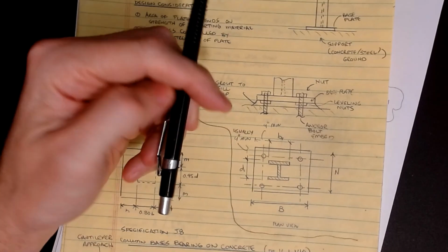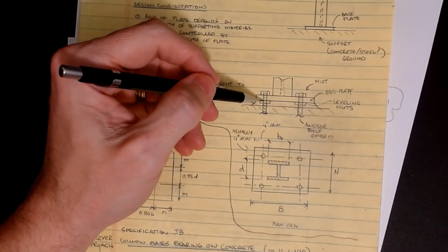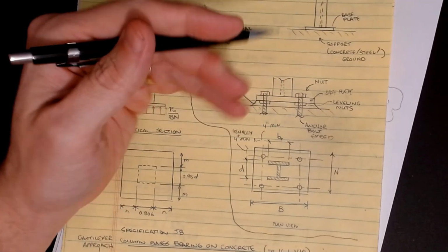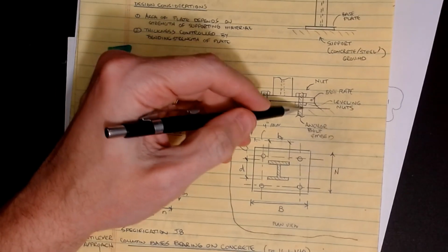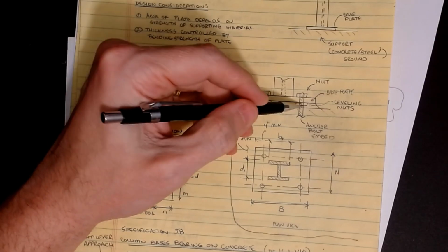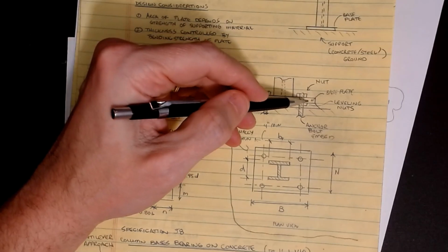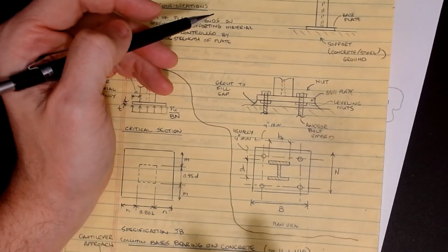And so these are what we call leveling nuts or leveling screws or something like that. And then once that's set, they'll come in and they'll put a nut over the top of this thing just to hold it and lock it in position. The gap then is filled with some sort of grout or cementitious material in order to fill the void and, again, allow all of that load that's coming into the column to get passed through the plate into the grout, which then loads the concrete down below. It's all kind of the same idea.